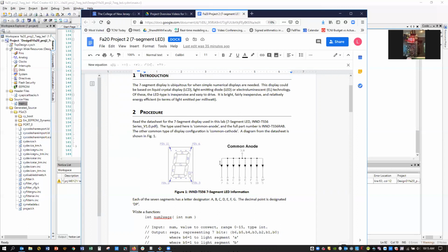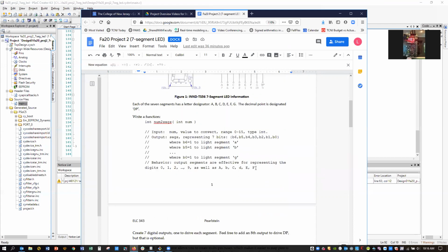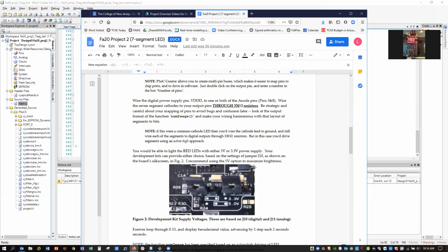These red LEDs typically drop about 2.1 volts when they're conducting. Different color LEDs have different forward voltages. Red LEDs are about 2.1 volts typically, but whenever you're doing anything like driving LEDs, you should read the data sheets and find out what the voltage is that you'll need. What else is there to say?